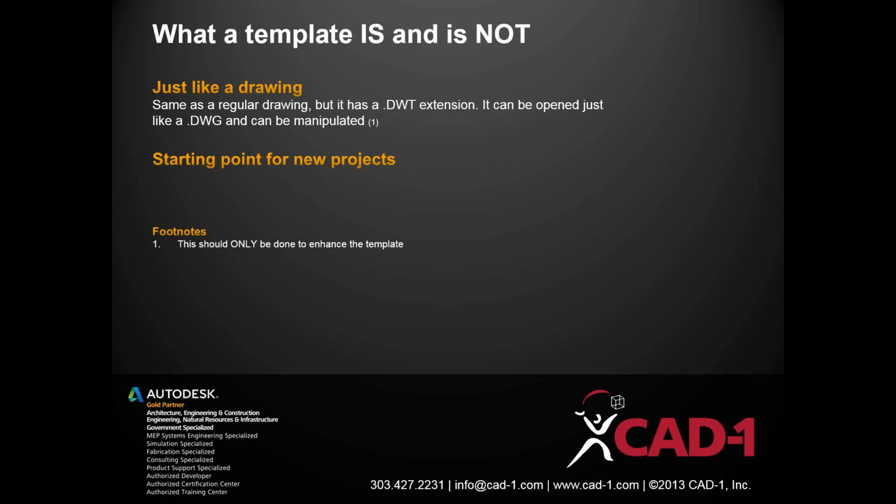Okay? Now, when I talk about opening the template, you can hit the open command and you can open the template. You can modify it and work with it, but I do throw the footnote in there. Hopefully everybody can read the footnote. You can open a template, but this should only be done by the person who's working on the template, creating the template, preferably a CAD manager or somebody like that. That's the person who needs to open the template and modify the layers, add layers, create text styles, do that kind of stuff. Nobody else should be opening the template. Everybody else should be using the template.